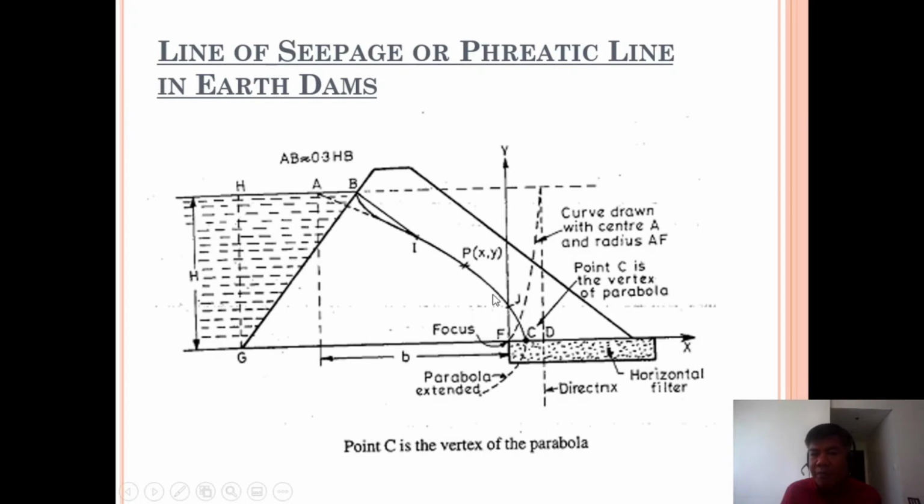So, drawing now this parabola going here, if you have this filter. If you don't have this filter, it's very easy because it is somewhere here also. But it is a different method if the seepage will go out on these two. Still remember in the previous slide, the seepage can go out within this area, which is a maximum of h over 3. So if you have the drain, it will go here. And this becomes the center of your